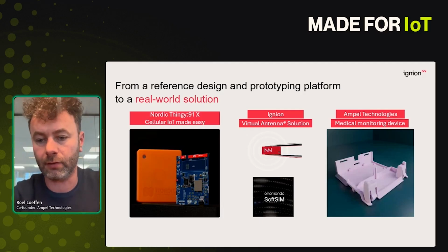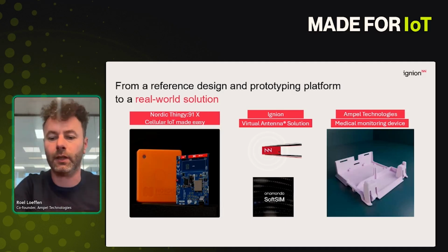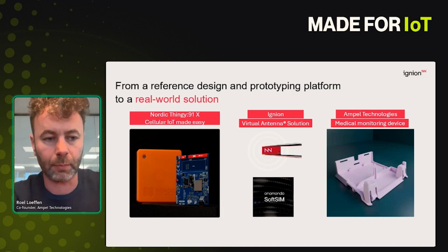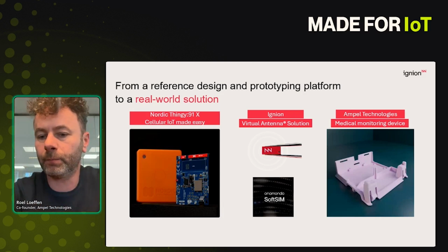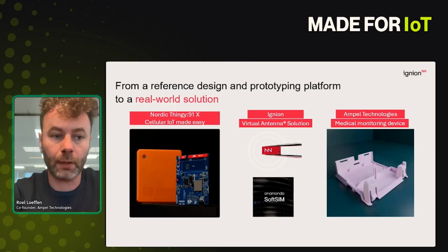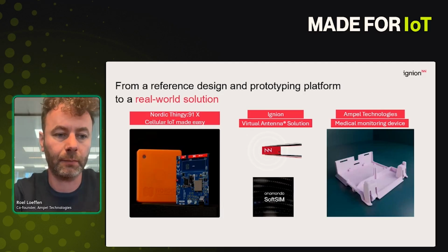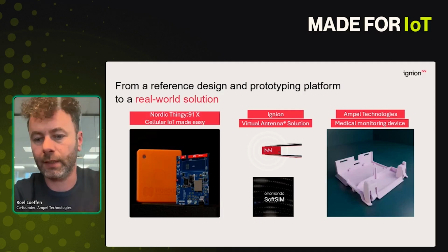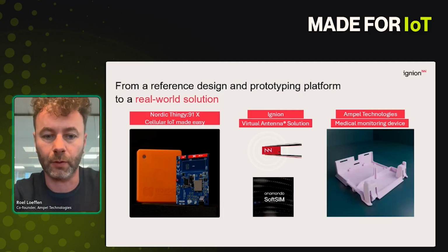With regards to sensors, we have audio sensors, so basically a microphone. We also do some signal processing on what we receive with the capabilities of the 9151. So we wake up once a day, we send the data we collect within this minute to the nRF Cloud, and that's basically it. So most of our energy is consumed during sleep mode.